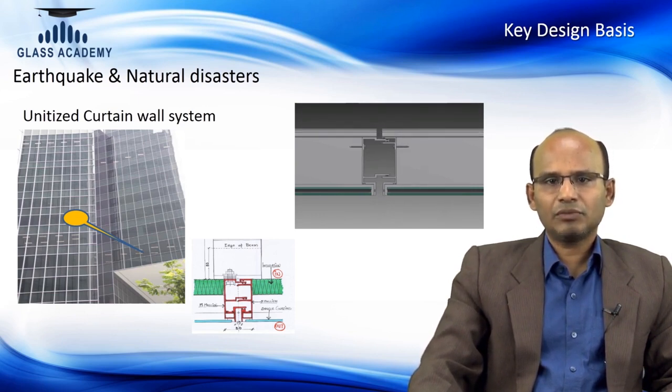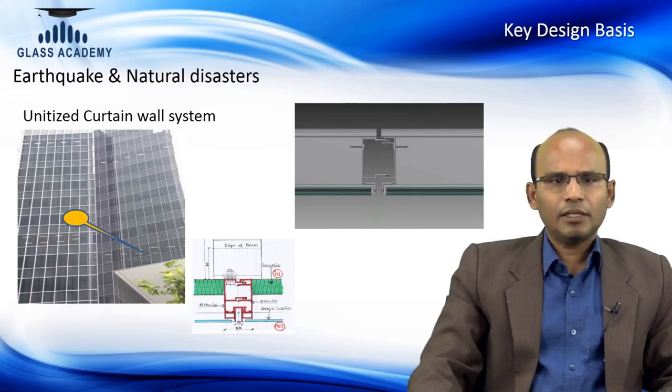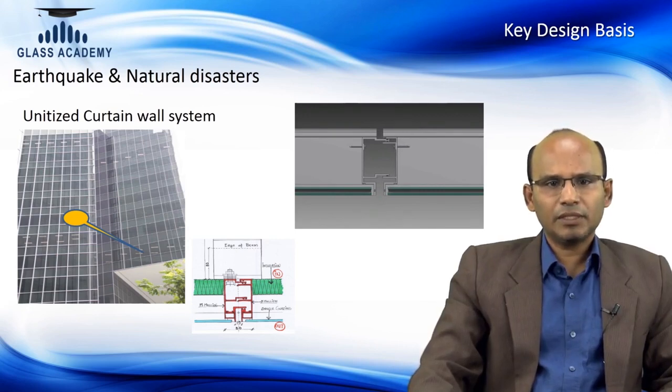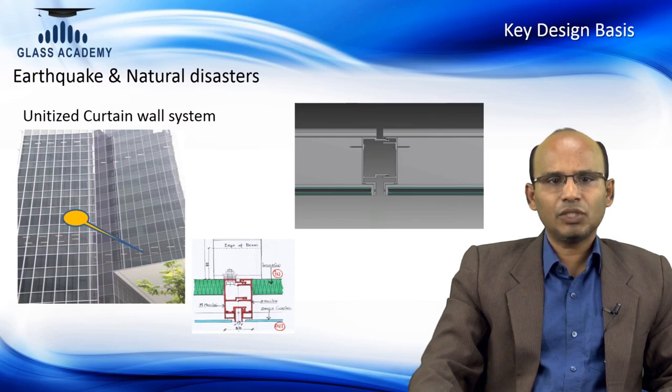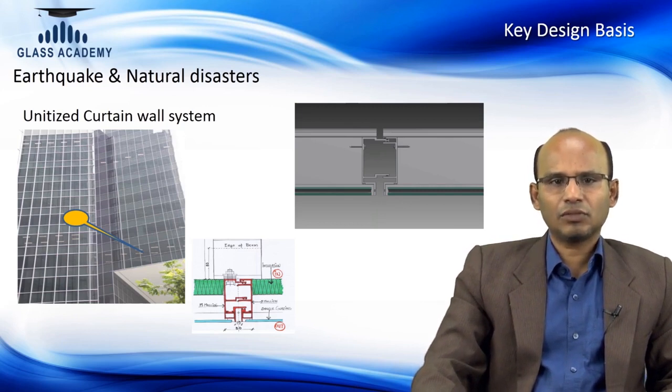In our previous slide we have seen the building swaying. When the building is swaying, this will impact the horizontal movement of these joints. And continuing with this, when the building is moving, the engineer needs to carefully check the joints. Unlike other building materials like concrete wall, there is no primary joint on the surface except where it is interfacing. But curtain wall or glazing or cladding has lots of joints along the face of the building. Hence, the joint design is one of the critical aspects here.